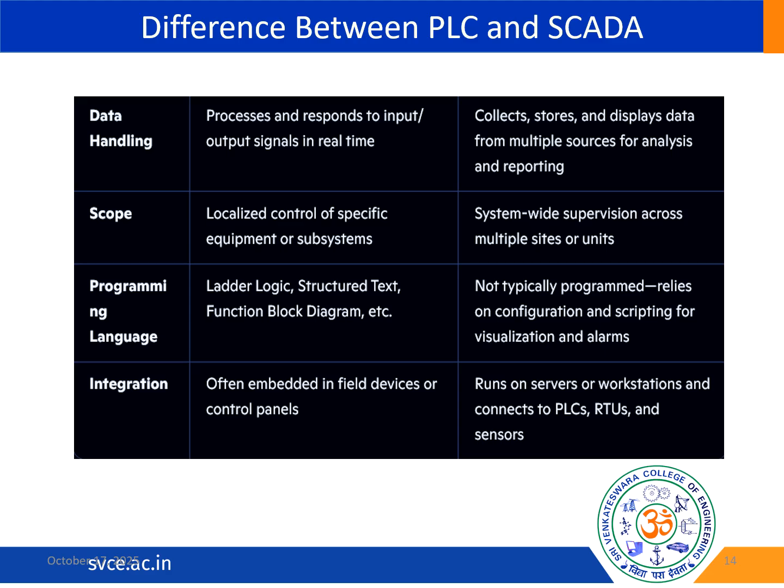For example, we can say the conveyor belt has stopped, and our right outputs, for example, start the conveyor belt. Depending on how it is programmed, everything has to be considered here. So a PLC forms part of a SCADA network, asynchronously receiving and executing certain commands from SCADA, for example operator commands like stopping the pump. These types of examples can be considered, and the PLC is used in the SCADA network as a source of data.